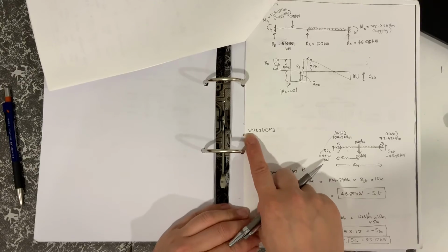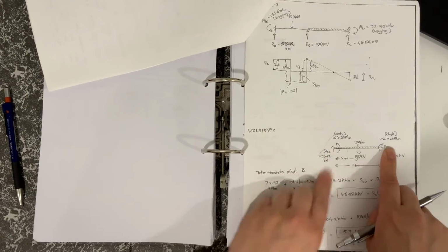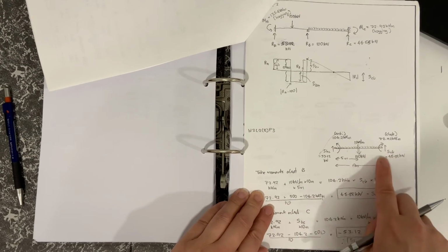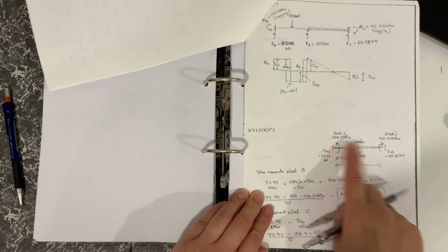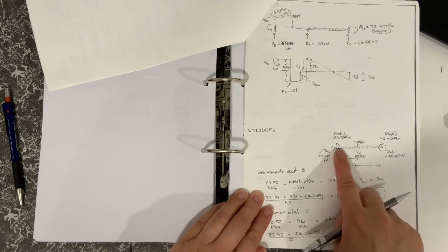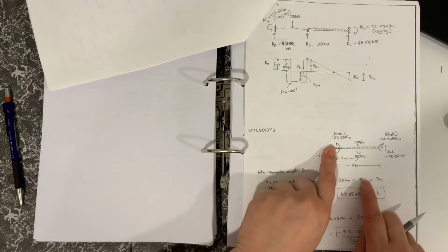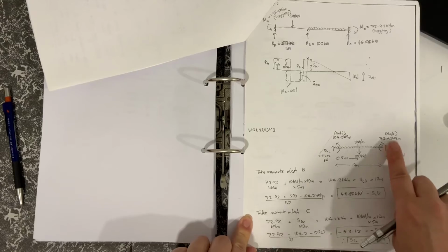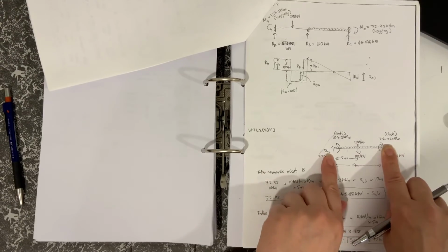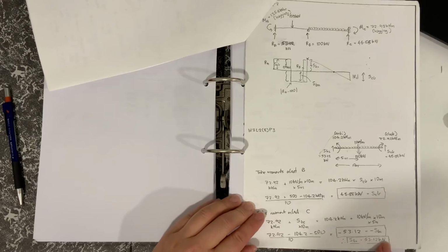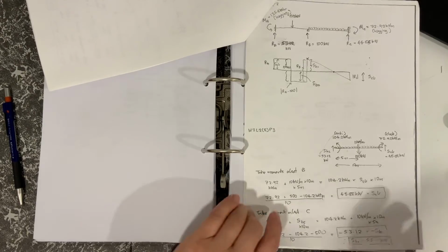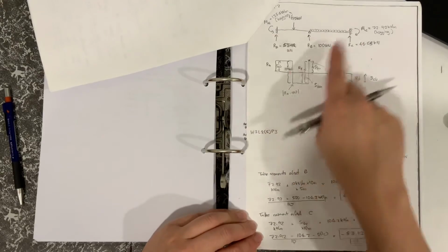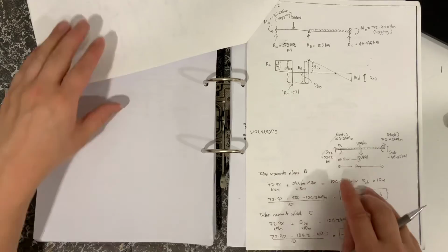Then you can do the same on the other side, which would be span BC with the load going down. So again, we know what these are, because these are the reactant bending moments, and the load is a UDL, so you can take moments about B, and that would give you SCB, and then you could take moments at C, and that would give you SBC. So you can see the calculation laid out here to get these, and then from there you could transplant that onto a shear force diagram.